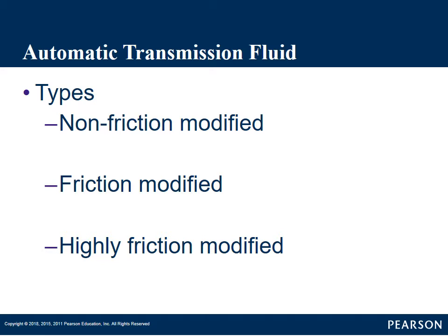Types of transmission fluid. There are three basic types of automatic transmission fluid: non-friction modified, friction modified, and highly friction modified. The non-friction modified are transmission fluids that didn't have any friction modifying additives put into them. To my knowledge, no current vehicle is using that type of transmission fluid.